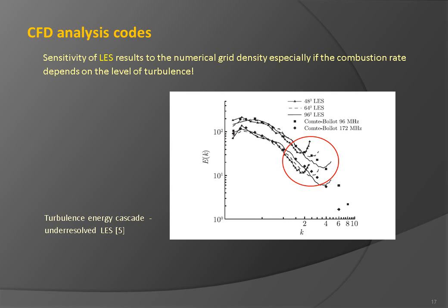In fire modeling, LES models applied to a coarse numerical grid will lead to increased mixing, further promoting combustion. It has to be said that RANS turbulence models are much more robust and do require a less dense numerical grid.